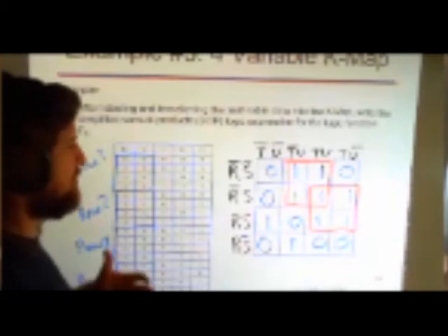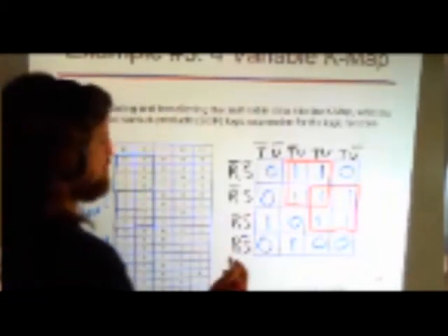And now, to hit upon what Mason was asking about earlier, we can actually reuse some of these numbers. Right here, I saw a different group of 4 I could have circled. And just because a 1 was used in one of my circlings doesn't mean it can't be used in that other circling. So I'll include that 1 in both of those min terms, both of those circles. And I can use that trick with my wraparound procedure.